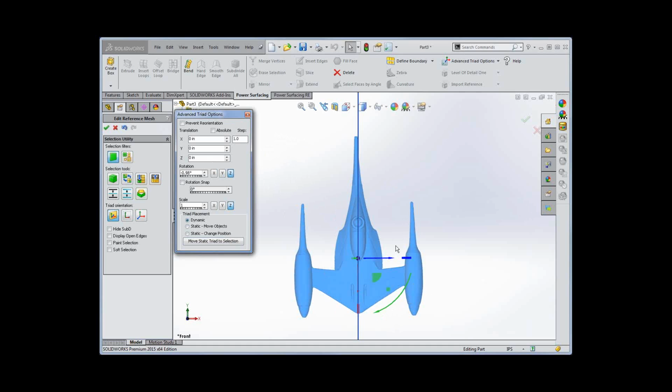At this point, the other thing you can do, and I'm not going to show you just because it seems to be waiting for me, and I'll probably just close and restart to make things quicker. But the other thing you can do is select parts of this and delete them. So if you had a really bad bubble where it didn't scan well, you could delete it. Or say you've got something like this dome on the, I don't know what that is, probably some little guy with a weapon in there. You could delete it and do your retopo and then add that part back in with a SolidWorks feature, which is going to be a lot more accurate.